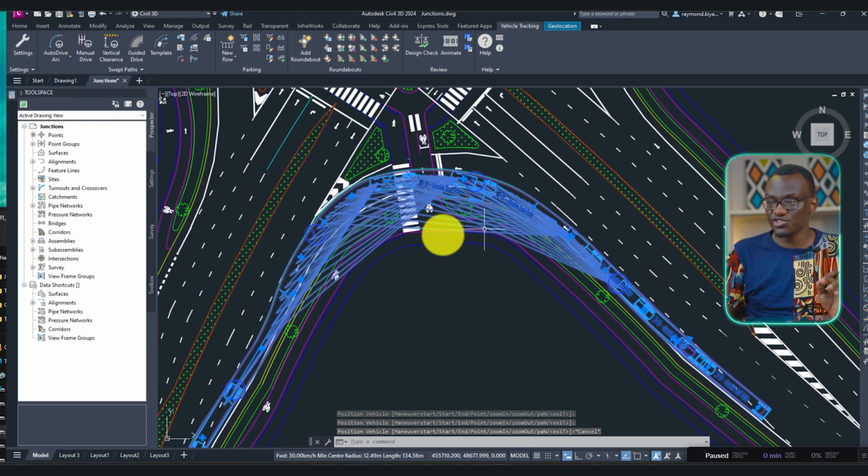And you'll be able to design the junction in such a way that, okay, in that section, let's make sure the shrubs are shorter. They shouldn't be able to affect sight distance. And also, you design the junction in such a way that there should be no building. There shouldn't be a building or anything else obstructing.